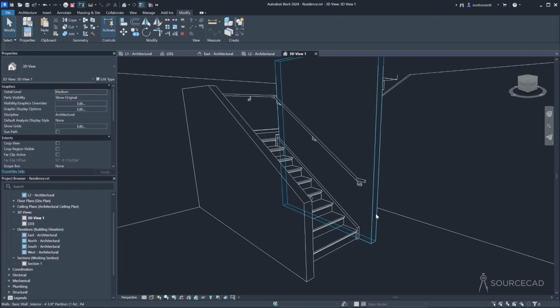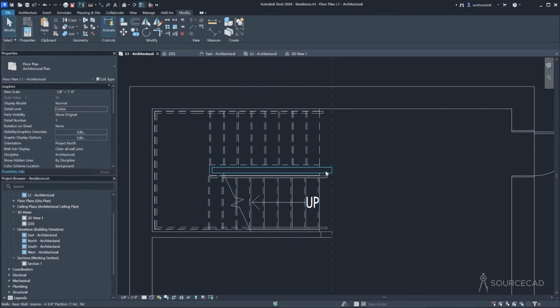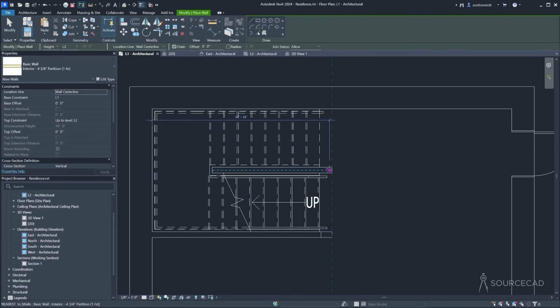All right, now over here, I want another wall to create this kind of space underneath the stair. Maybe we can use that for a space for the water heater. So I can go here and create a similar wall. And Revit cleans up the walls. You see how I don't have to really worry about exactly where that wall terminates? I just have to bring it into the volume of this wall and Revit will clean it up.